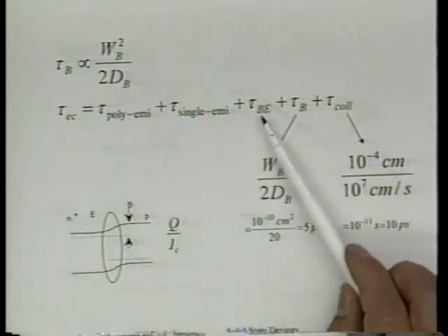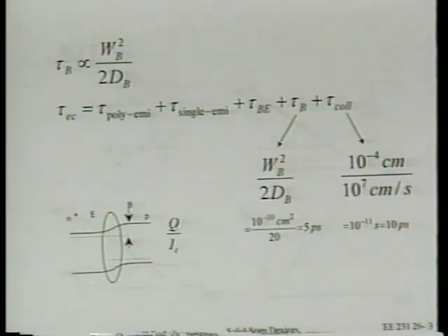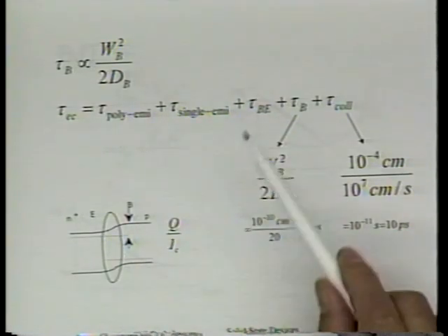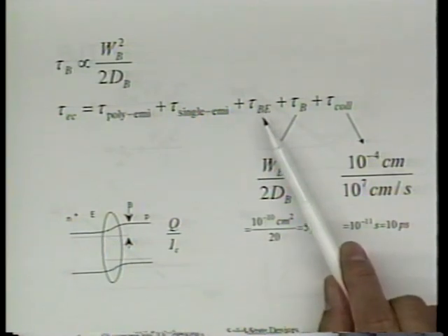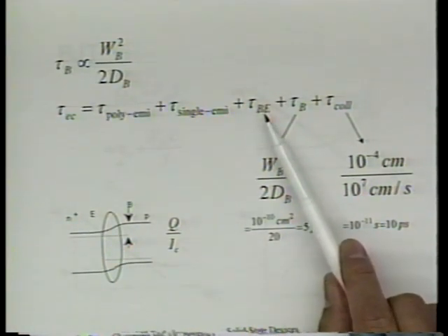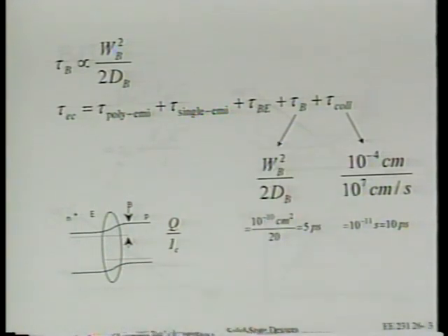Okay, the base-emitter junction also stores charge. All right, the base-emitter junction stores charge. If you draw an energy band diagram, you can convince yourself there are actually more electrons stored, a higher electron density, in the so-called depletion region between emitter and base, and in the base itself. Try to convince yourself of that. Draw an energy band diagram, all right? See where the Fermi level is relative to E_C. Okay, here. We're looking at this diagram.